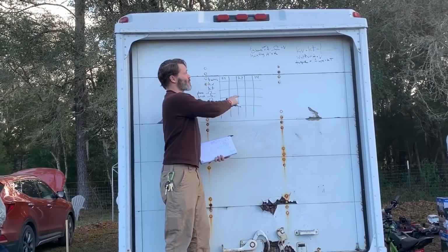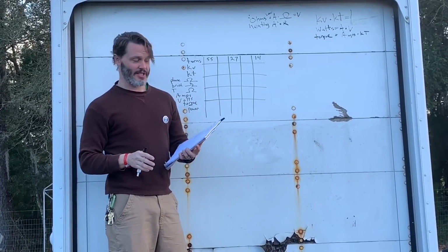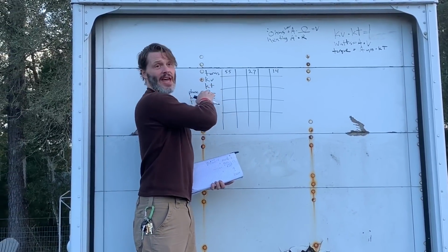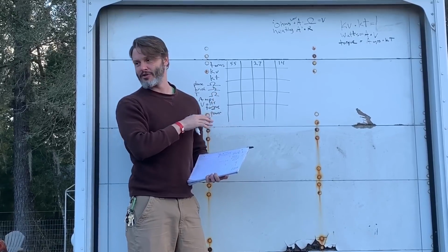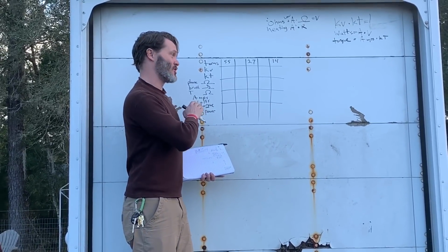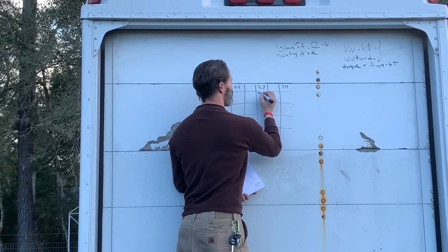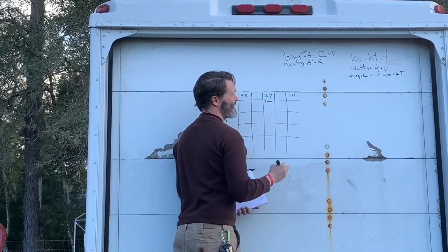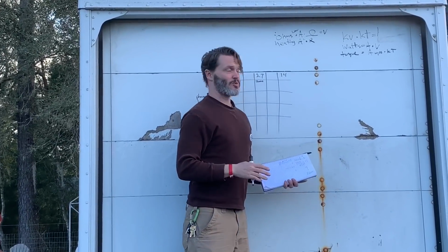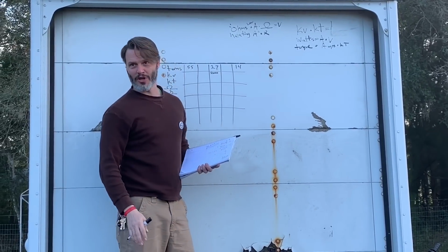So what we're going to do is assume that a 27 turn is where we're starting from, and we're going to make all the formulas based off of that. I know that the KV of a 27 turn motor is right about 2,000 KV. It changes a little bit with different construction, but more or less we can assume that's about the speed, especially if we're comparing to a brushless motor. So it's 2,000 KV. For our torque constants, we're going to scale this one today. We're not going to use hard numbers. We're going to use easy numbers.